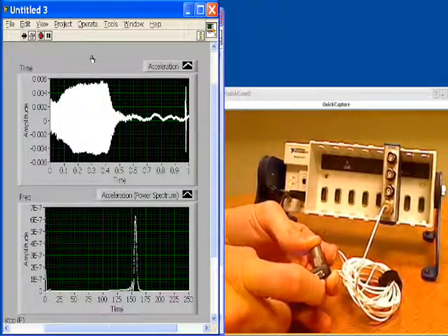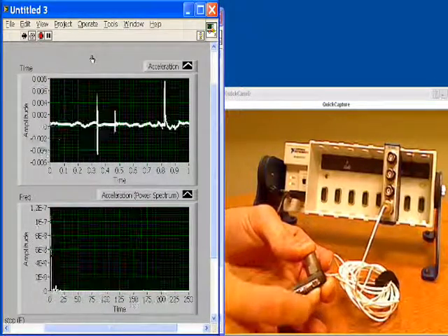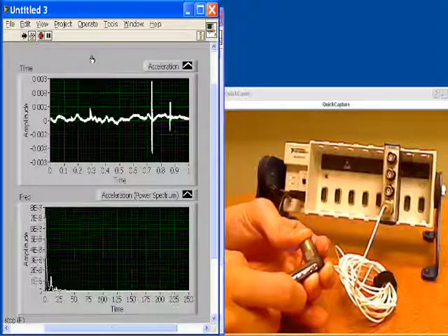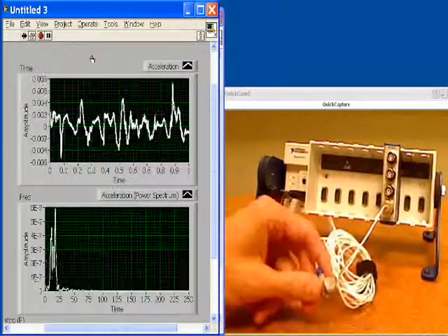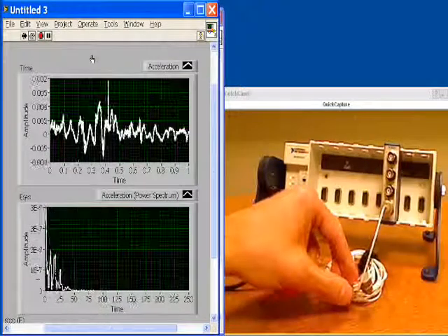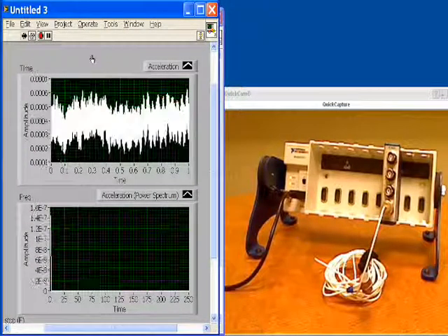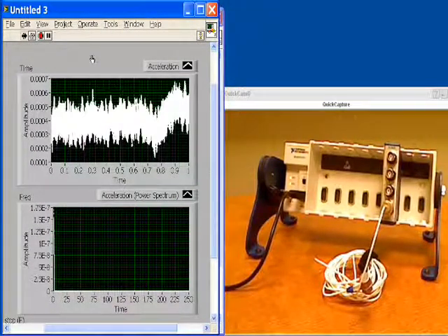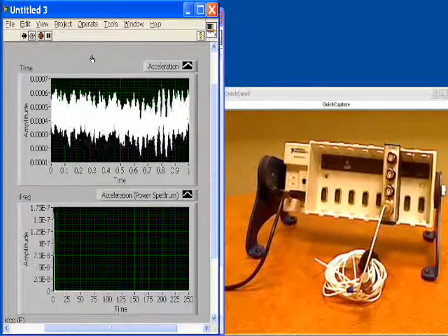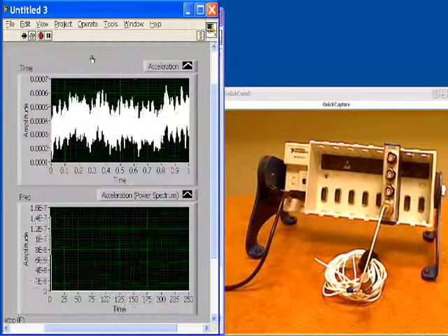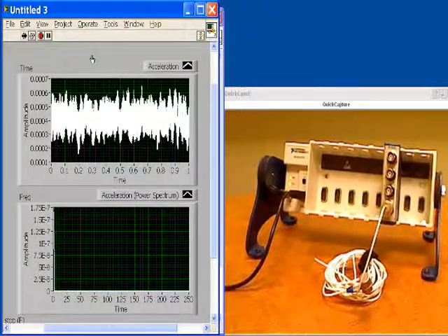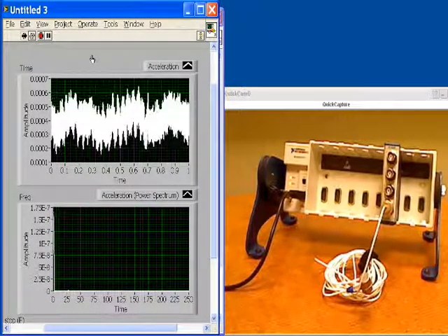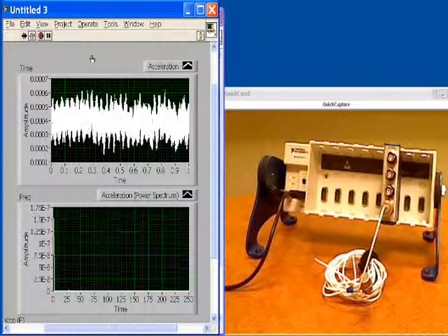And so you can see real quick we set up an acquisition and analysis system using LabVIEW and CompactDAQ to measure frequencies. Now because this module can measure up to 50,000 samples per second, we can acquire frequencies much higher than 160 hertz. We can go up to the 25 kilohertz range, and all using the DAQ assistant and using LabVIEW. And so that is how you take an accelerometer or vibration measurement with CompactDAQ and C-Series modules.